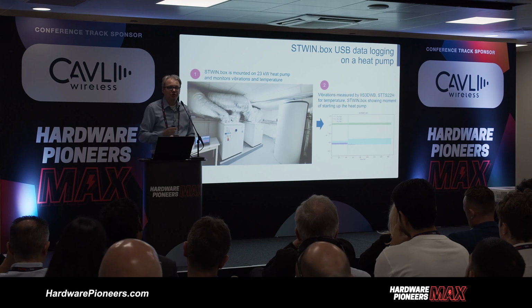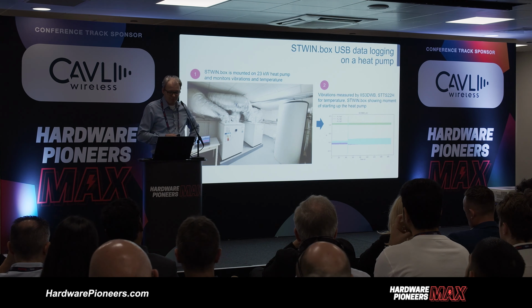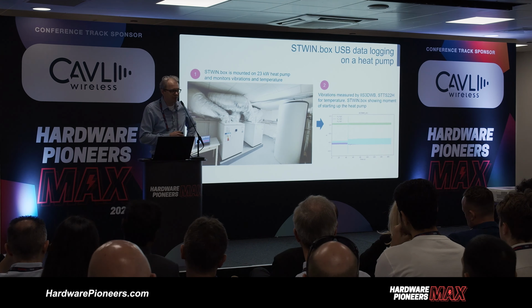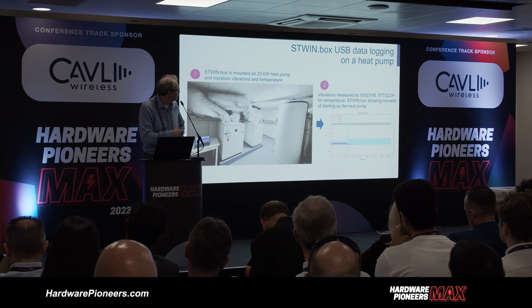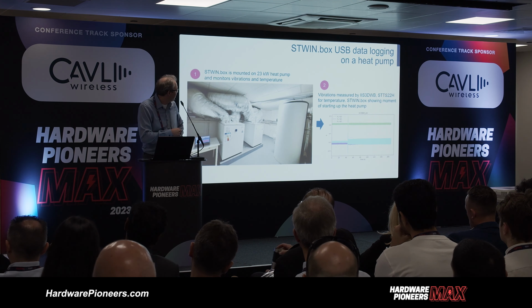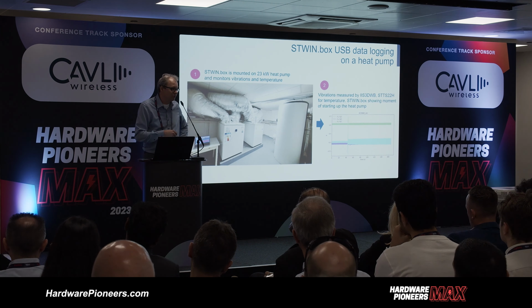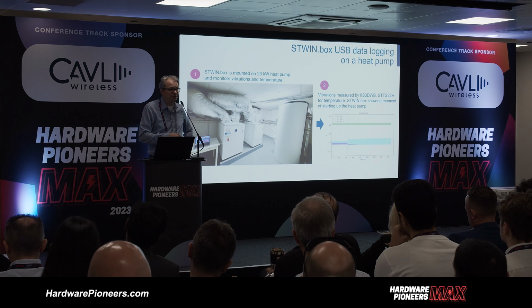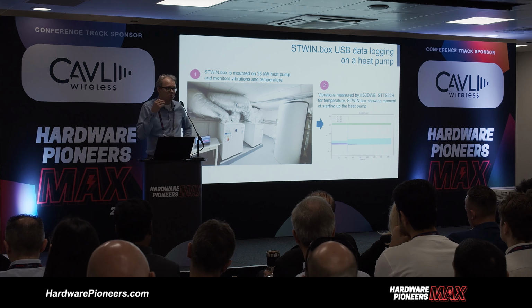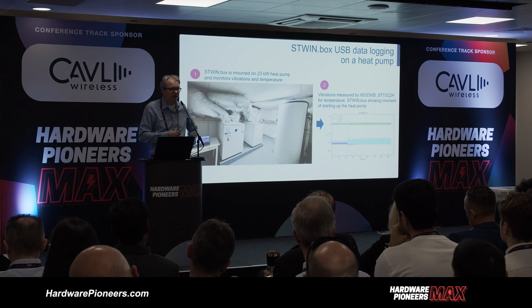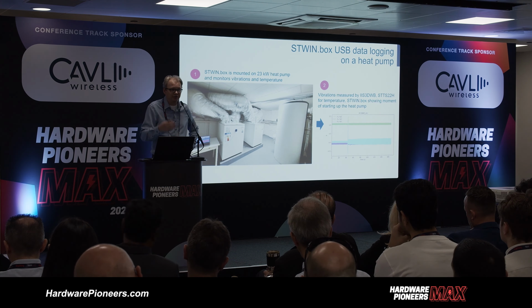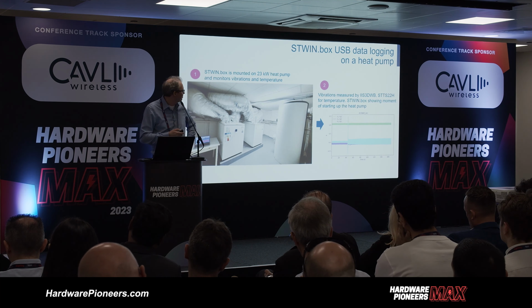All right, so based on those measurements that we did in the lab, just to show one more practical example, this is actually from an apartment building, a 23 kilowatt heat pump, and the same principle is here. Now we just mounted it on the outside chassis of this type of equipment, and you can see in here again in the Z-axis, especially when the compressor is starting in this type of equipment, that it will start to create vibrations, and then over time this can start to change.